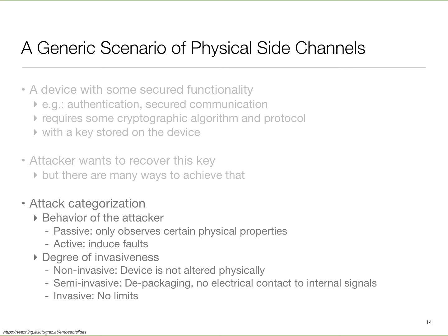Then there is how invasive you allow the attacker to be. Am I allowed to change something about the device? Am I allowed to run my own program somehow? Am I allowed to connect some peripheral and whatnot? And then also oftentimes, particularly with military devices, they have tamper-proof packaging. They may have sensors to detect tampering. So the question here becomes, what degree of tampering am I allowed to do? Am I allowed to open the shield? Am I allowed to probe the pins on the circuit board? So there are various degrees of intrusiveness that you might imagine.